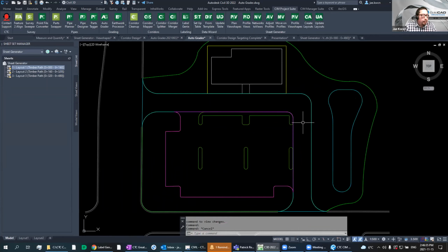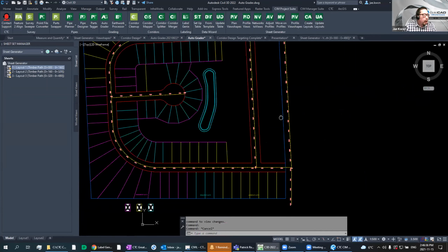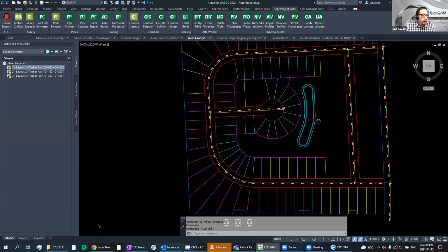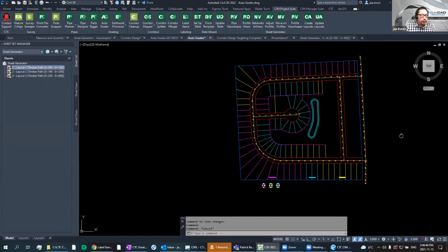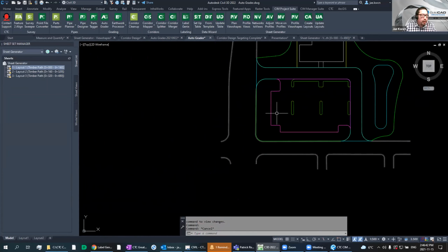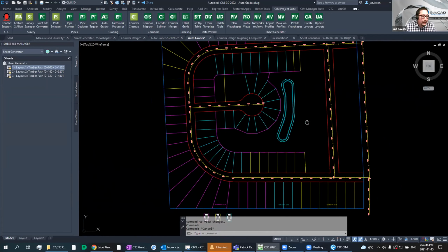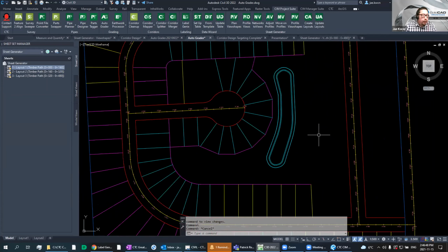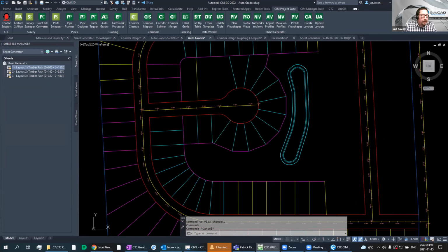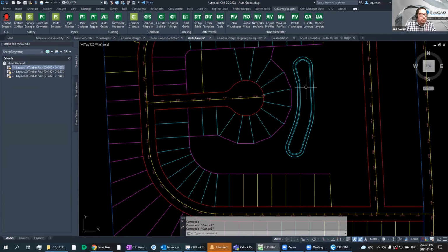Okay, so I'm going to go over here. I have 2 scenarios at the commercial site that we looked at earlier. This time, let's take a look at a subdivision. So with the standard out-of-the-box grading tool, you can set up grading sets, right? So you can basically go through different steps.